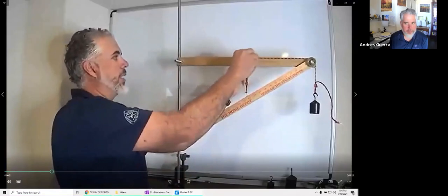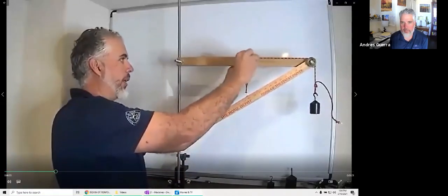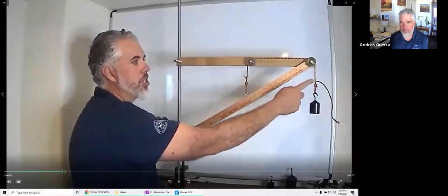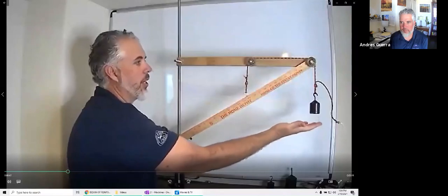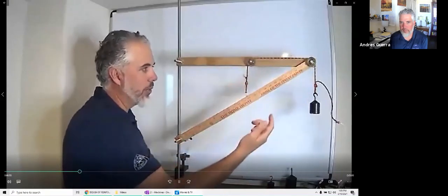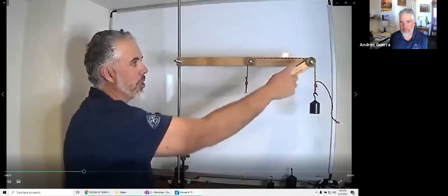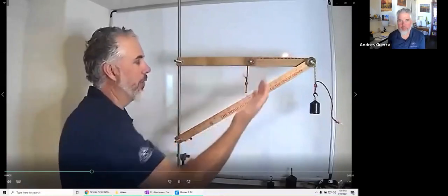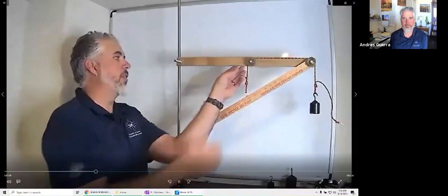Well, first, let's look at what's going on at those frictionless pulleys and how they transfer forces onto the rigid objects. If I take this frictionless pulley off right here, we know that since these are frictionless pulleys, the tension in this rope is all the same. This is 0.5 kilograms. In our example, it's 50 kilograms. So we can convert that into a force by multiplying by gravity, and that would be the force that's along this whole cable here. And so we know in each segment of that cable we have that 0.5 times 9.81.